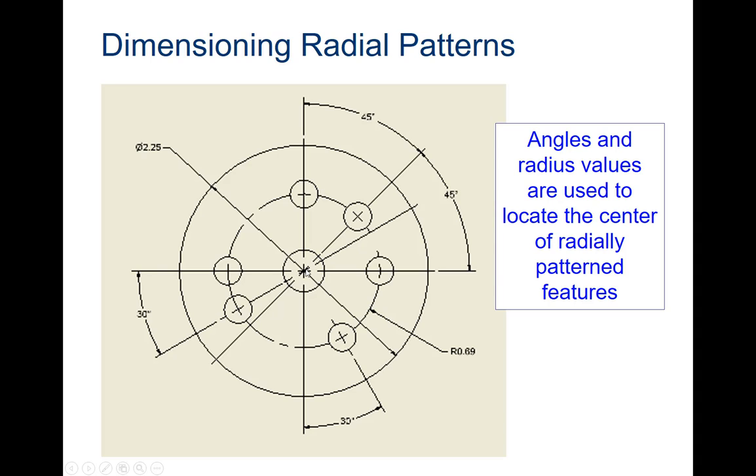So we've done this before. We drew some construction lines in. We dimensioned the construction lines. Then we had a little point right here where these lines intersected, and that's where we placed our hole. All right, guys, so that is dimensioning in a nutshell. Remember, datum dimensioning, chain dimensioning. We prefer datum. It's a little bit more accurate.